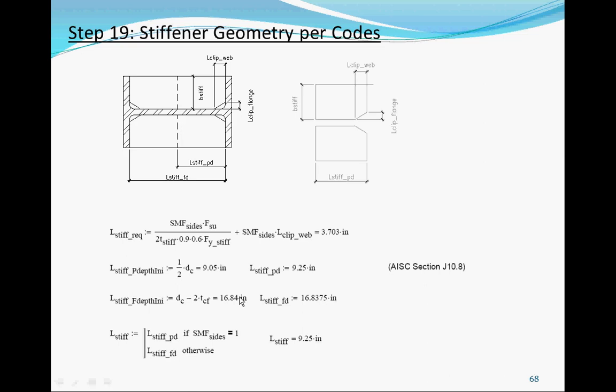Actually, whatever it is comes out, you should just call that number. I think it just rounded off to 8375. That's actually the length you need. If you call out full depth, it's for calculation purpose. For fabrication, when you take it to the fabricator, they will measure. They'll give you that depth because you don't want to be too short or too long. You cannot fit in there. For calculation purpose, you could round it down a little bit if you want.